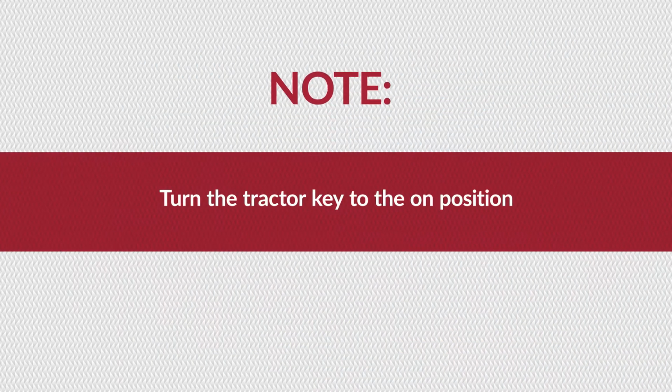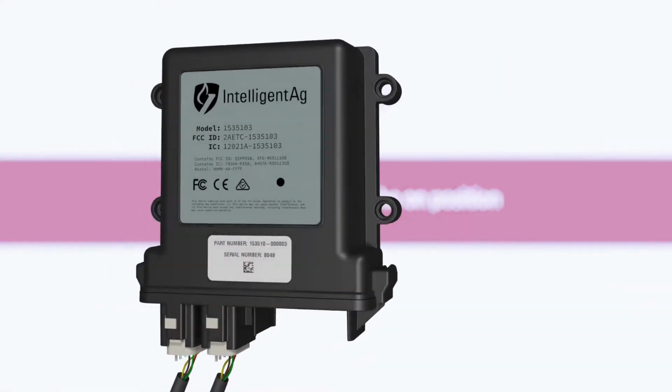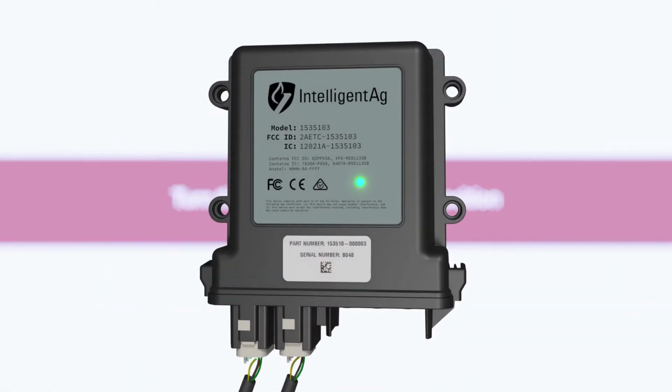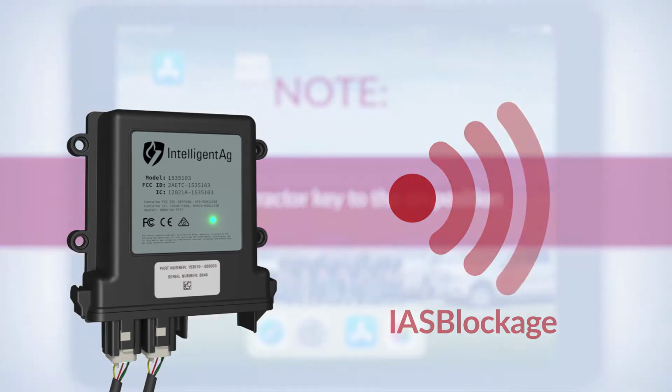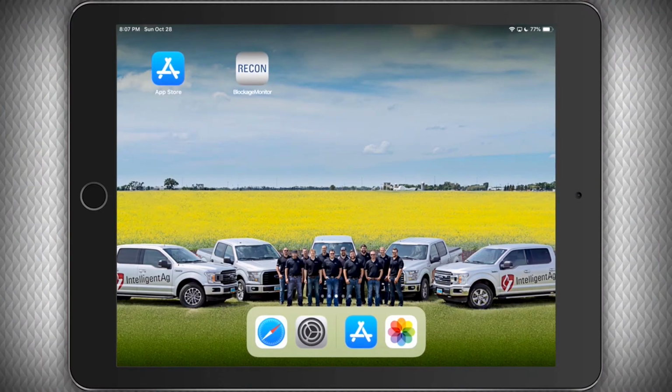Turn the tractor key to the On position. Once the LED on the gateway is green, the gateway will be transmitting the Wi-Fi signal called IAS blockage. You will connect to this network with an iPad in order to load Engage Zone Control firmware onto the gateway.